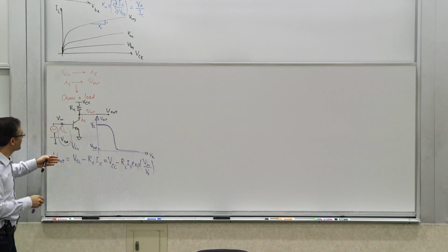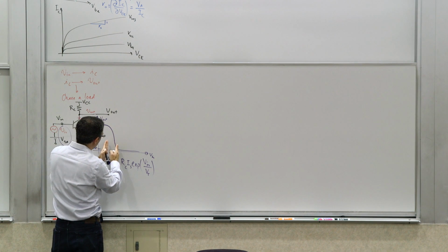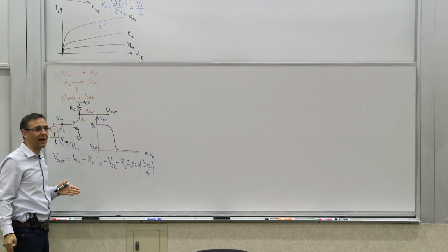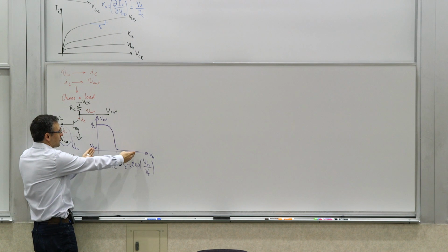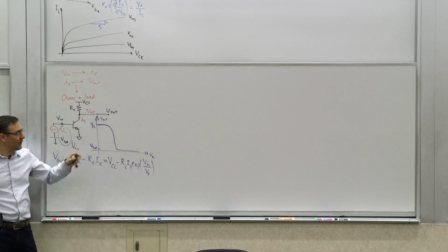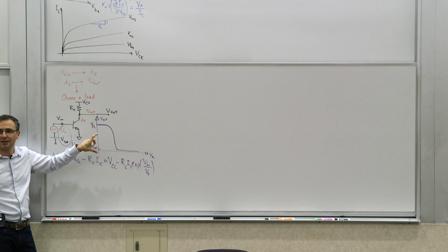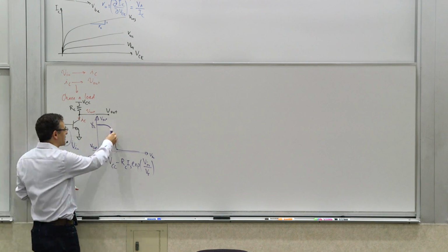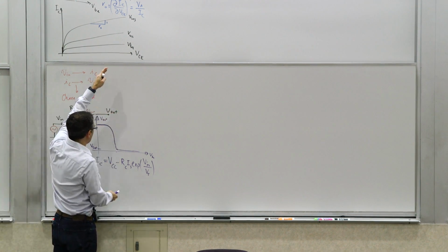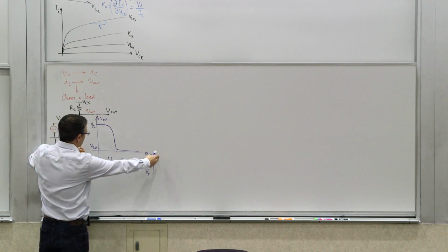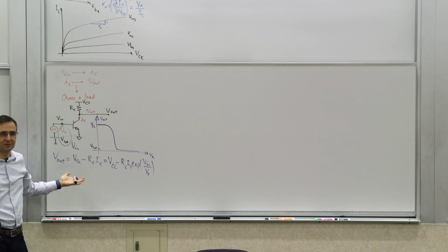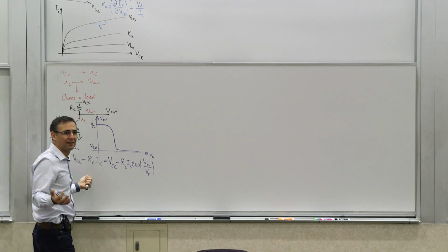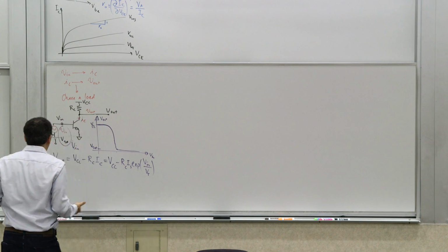And it has a limited range, as it should. Basically, if you have something with high slope, it cannot have a very large range with a given amount of supplies. So you can't have a very high range of operation and a very high gain if you have limited supplies. That's very fundamental. You can't have a very steep line that goes very long range horizontally at the input without having a long range vertically. It's a basic fact of math. Right? So, okay, that's what it is.